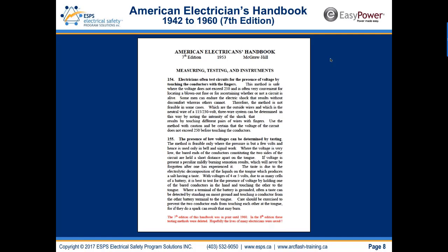In general, other workplace hazards weren't acceptable, but specifically in the context of shock, this work practice was the way it was. And I do discuss that historically, electricians have been taught to take shocks, and here's an example. We taught them to, and so they have considered shock as not an electrical incident, when in reality it is, and it is a near-miss incident that could have resulted in electrocution.